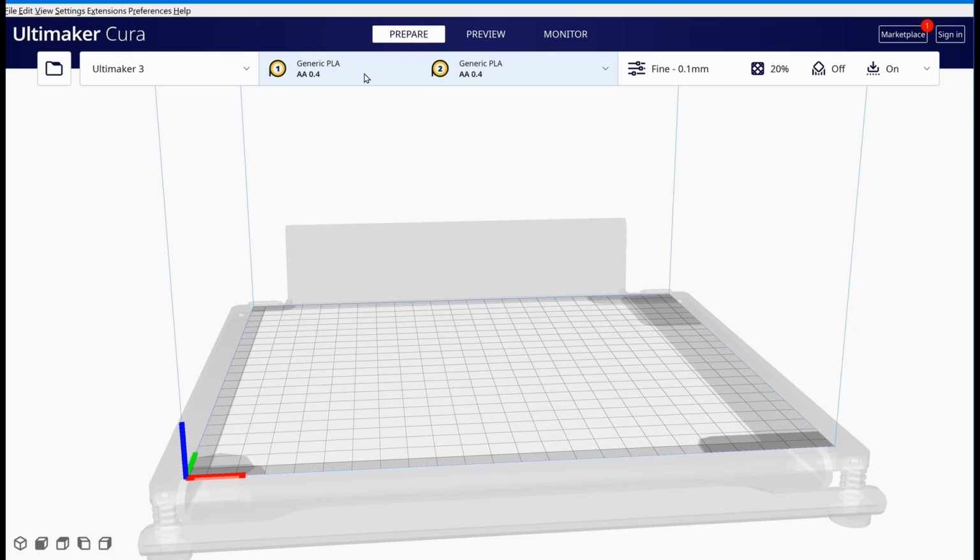In order to get the file onto the Ultimaker, there are potentially a few different ways. The one obvious and easy one is to actually put a SD card into the lab computer, move the file to the SD card, and then the SD card loads directly into the 3D printer. Now, for me at home, I actually have a Raspberry Pi hooked up to my 3D printer, which controls the 3D printer, and it also has a camera hooked up to it. So once I'm 3D printing, I can actually watch the 3D print on a browser anywhere that I have wireless range in my home. But in this case, we're just going to set it up as if it's being done at school.